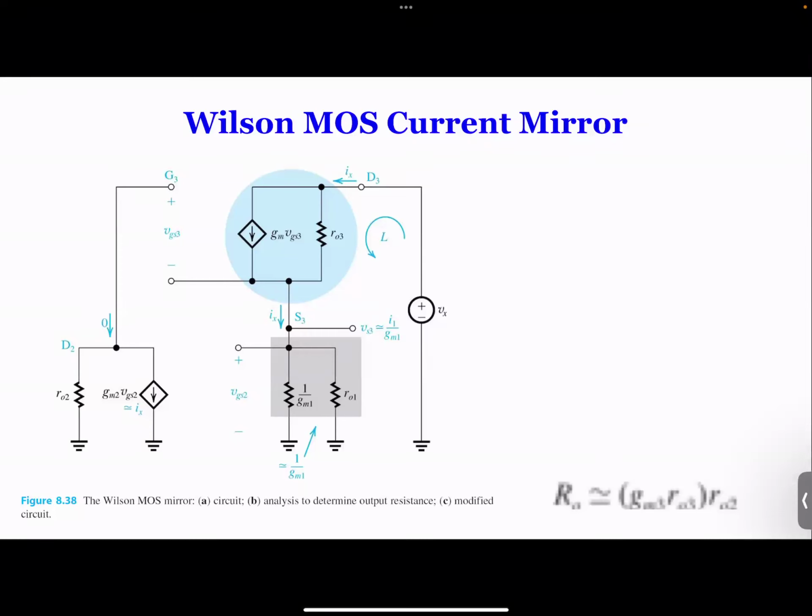Get the small signal equivalent circuit of the circuit and figure out what is connected to each terminal. Once you figure that out, then you can simplify the circuit and do the circuit analysis. So it really makes it simple if you can draw the small signal equivalent circuit. That's the most critical thing.